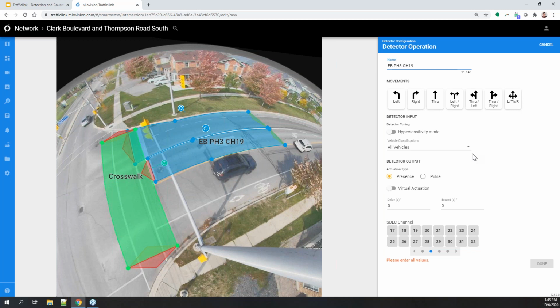on an offset of channels over to 17 through 32, which you can see down here. So channel assignment, again, is the important piece. This is just a label at the top, but down here we actually associate a channel to it. And so since this somewhat follows the same convention, just offset by 16, phase 3 is going to be our channel 19 in this case. But it could be phase 3 equals channel 3 or more. And so you can even toggle along the bottom to see what channels are available to configure. And you can see it goes all the way up to 64, but they're grayed out. That's because we only said use detector rack 2, which is our channels 17 through 32.